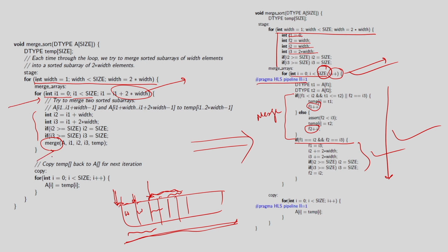Earlier I was applying the pipeline at this level, third nested loop, but I am actually applying in the second nest loop now, right. And also since this loop is a fixed size, is fixed for a program, I can actually get the all performance estimate of this. Okay. And also you can see here that memory read problem I have resolved, and everything is happening here. So, this again will achieve my PI equal to this loop pipelining initiation interval equal to 1, and this is the kind of best restructured code.